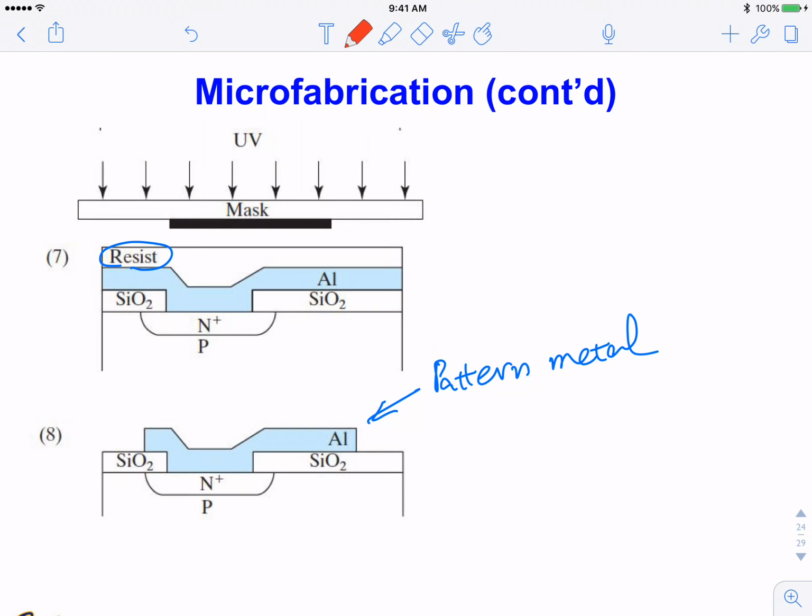Now, if you go to 10 nanometer transistors, somewhere the metal has to be very small. So if you have one layer of metal here, and you need to make a connection to it, you put in an intermetal dielectric, think of it like silicon dioxide. So you make a tiny hole, three-dimensional, and you deposit a particular type of metal that can go into the tiny holes.